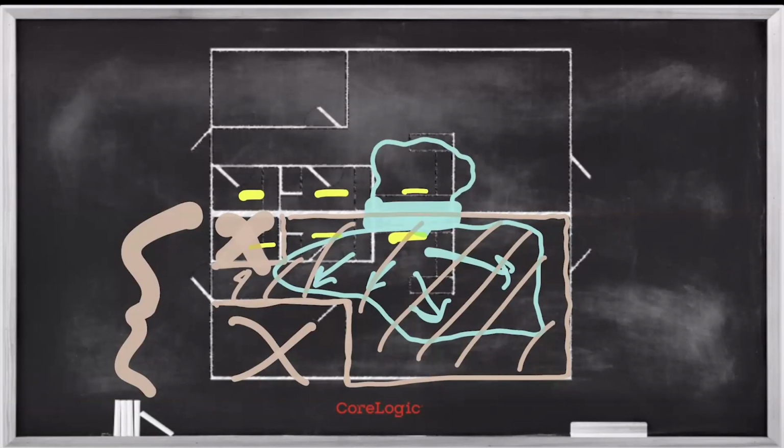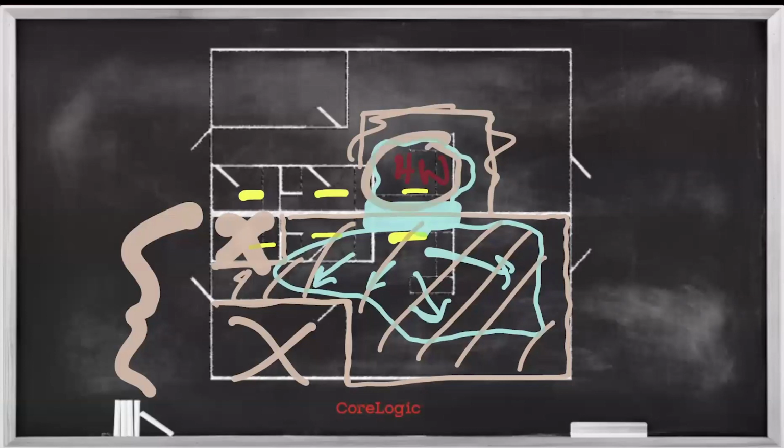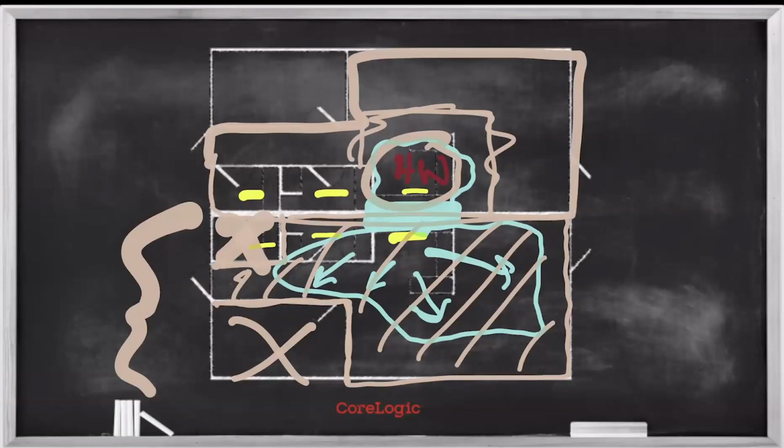Whereas on the other hand, in this space up here, if this was predominantly a hardwood floor that is impacted up here in the unit that's on the top side of this drawing, this would likely be a class 4, right? Especially if I can contain down to the area that is actually affected and maybe use a temporary barrier so that I'm just dealing with this area. However, it could also be a class 1. If I leave this entirely open and do not construct a temporary barrier, then the percent area affected here could also be considered a very low percentage of this larger area that I'm dealing with.